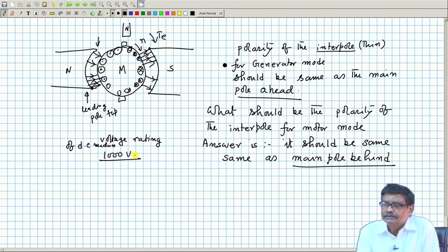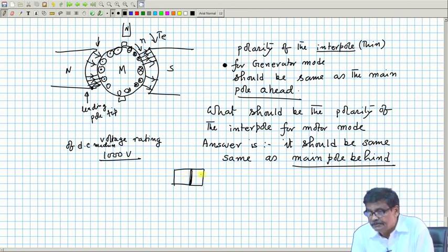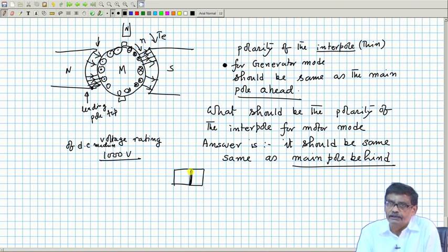So, mica has a breakdown voltage of its own, and with two commutator segments side by side with a thin layer of insulation, a large voltage means the voltage existing between the commutator segments will also be large and the machine will fail.